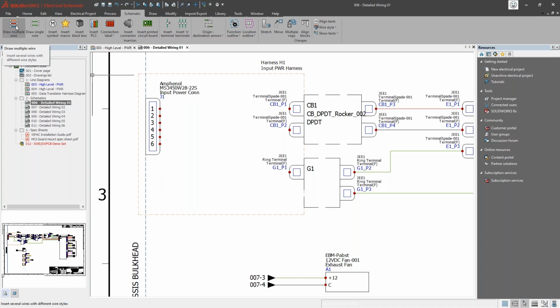What's the difference? Well, the main difference is if I'm doing large cabinet design, or not necessarily even large cabinet design, but if I have a large bus that I need to draw out, I don't want to have to draw phase 1, phase 2, phase 3, protection, everything separately. I can draw that all in one shot. So that's what this is for. You can define each one of those legs. You can turn off a leg. Maybe in one case you have phase 1, phase 2, phase 3. Another case you're only using phase 1. Well, you can check those on and off as necessary.